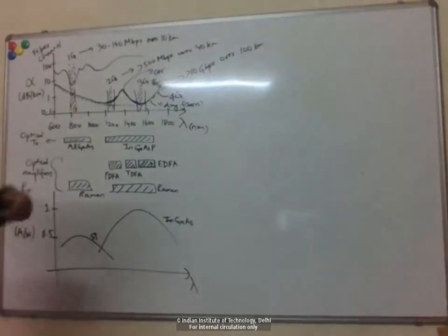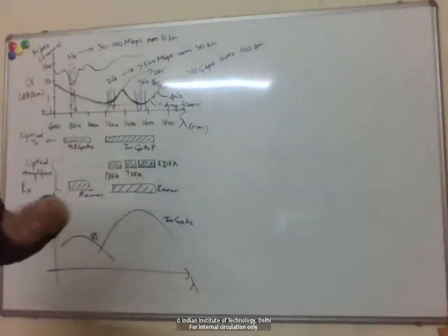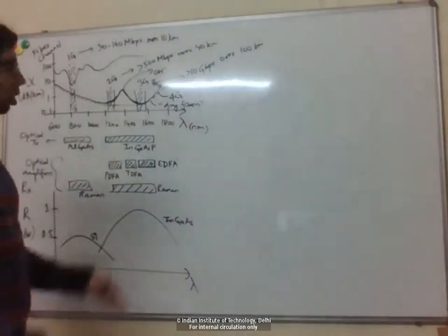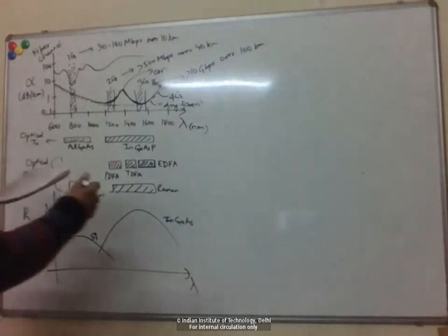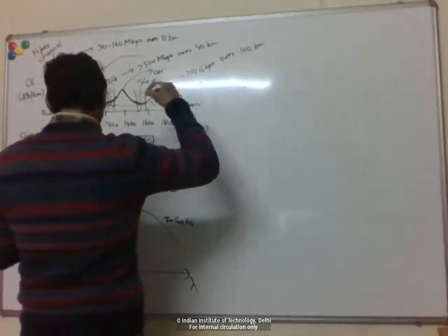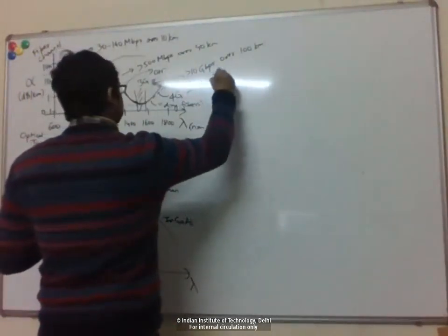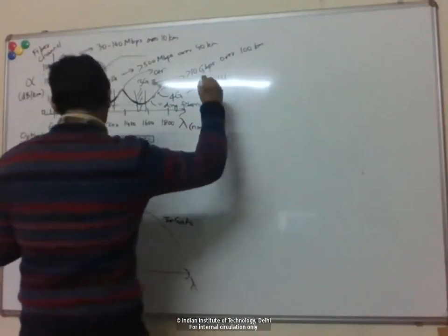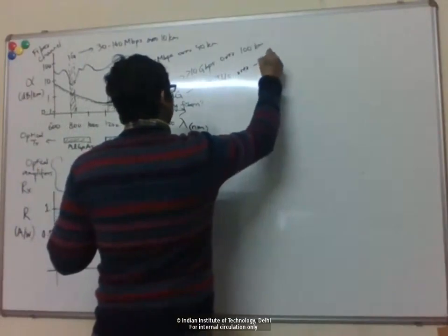right? And for example, using wavelength division multiplexing, you can have different wavelength channels, each carrying its own data, so that you send them all out in parallel, right? So the total data rates you can achieve now are extremely high. So, current state of the art, people have demonstrated about 10 terabit per second over up to, let's say, 10,000 kilometers.